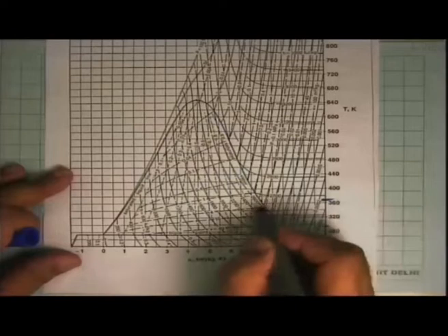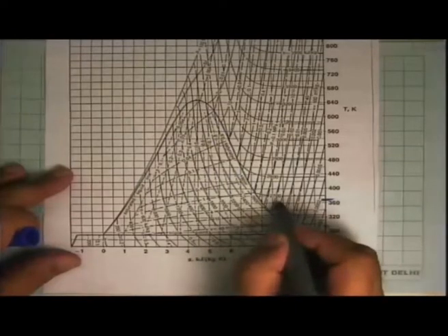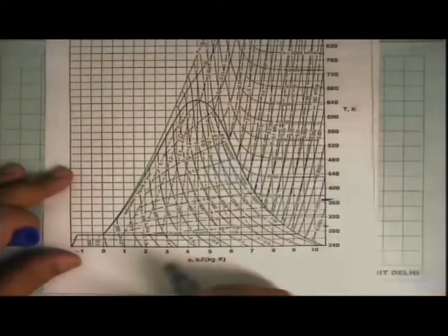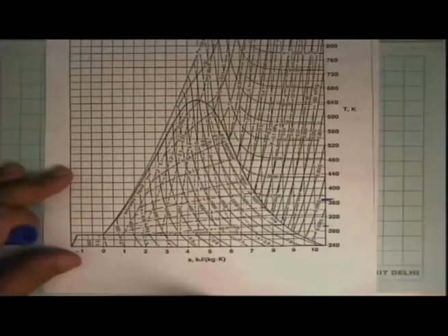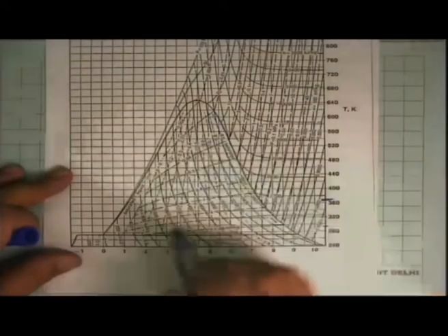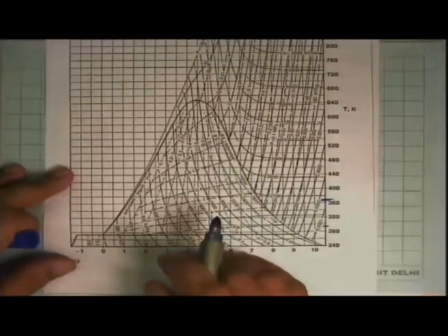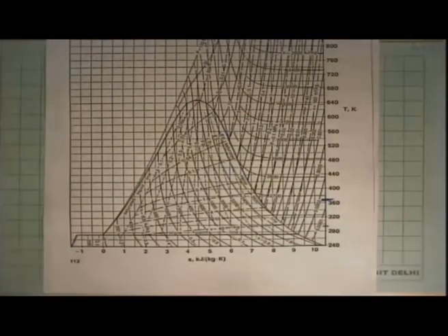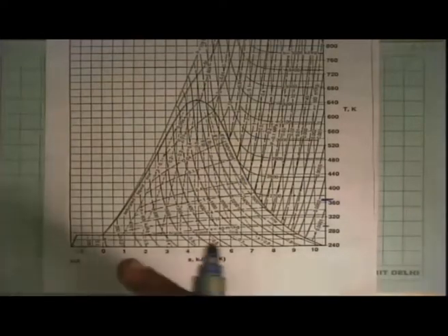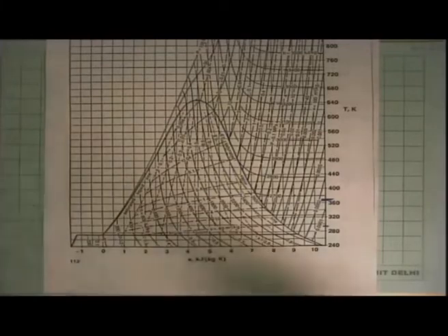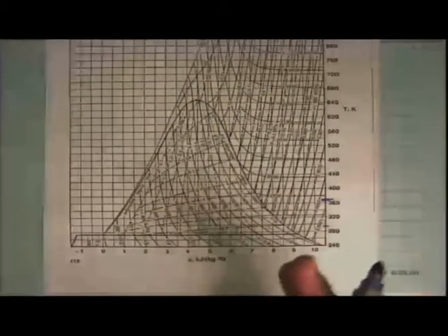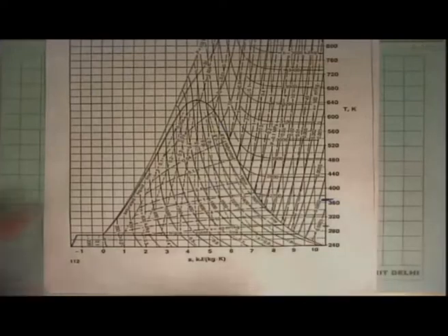The trouble is that if you look at 360 and you start looking at the numbers that come out, you'll see here that the specific volume is on the order of, it says 100 meter cube per kg. So this is very, very big specific volume. This is vapor at low pressure. It occupies a very large volume. So to get the same mass flow rate, we need very, very big pipes, many meters in diameter, before we can even make this thing work.